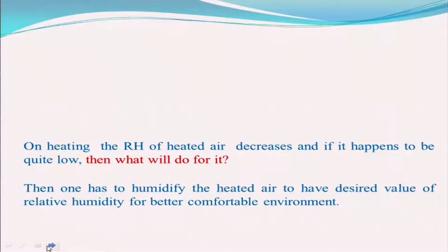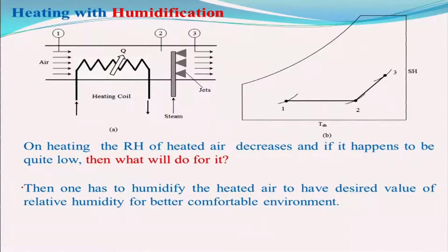What do we do? Therefore, in the winter season, when you use the heater in your room, you find dry skin more, right? That means you will have to humidify it. That means you add some water moisture so that you will not face that problem. As I told, one has to humidify the heated air to have the desired value of relative humidity for a more comfortable environment. Let us say heating with humidification, we can do that. You can think of adding, this is the heating coil, and then you can add some steam or some spray kind of thing, so that it can add moisture.